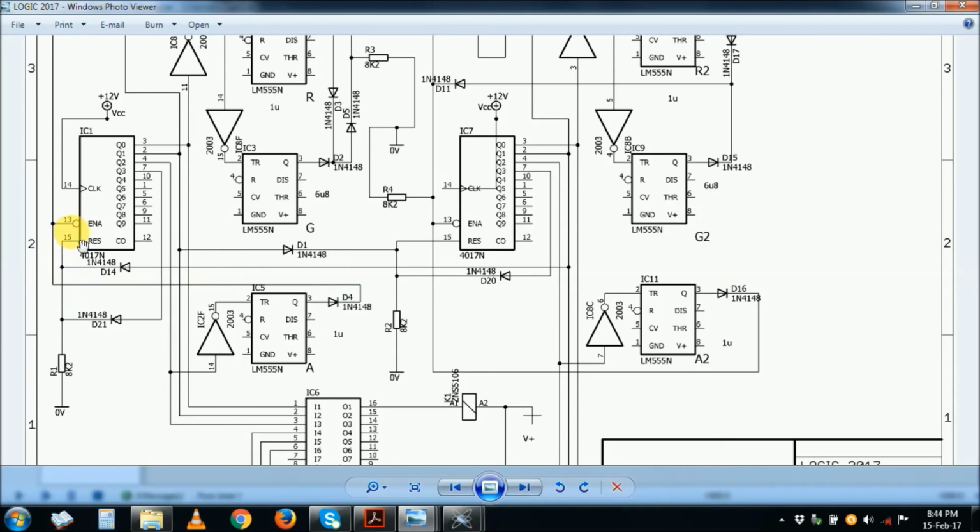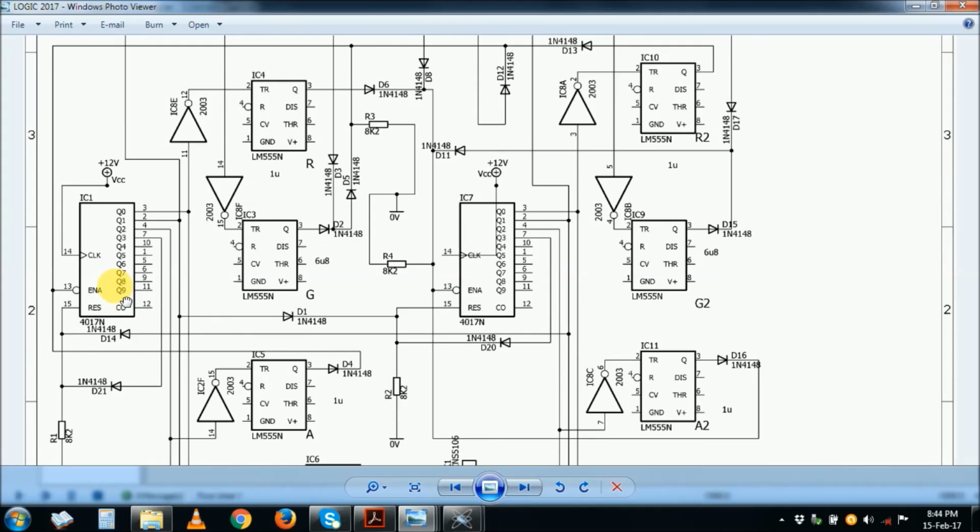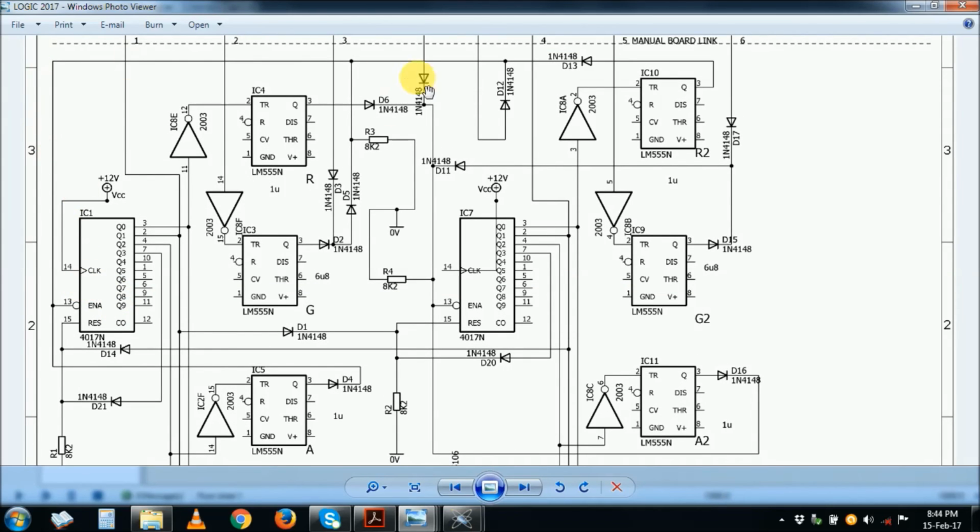Here it comes back to the strobe input, or the clocking input, of that IC. Here it can't go, it's all blocked that side, so it's going to clock this one from high to low, clocks to number 7. Number 7 comes back and resets the counter. And the counter is reset, goes from amber now to red, and remember this one is still red, and then the cycle starts again, a red here, another like that. So this is how it works.